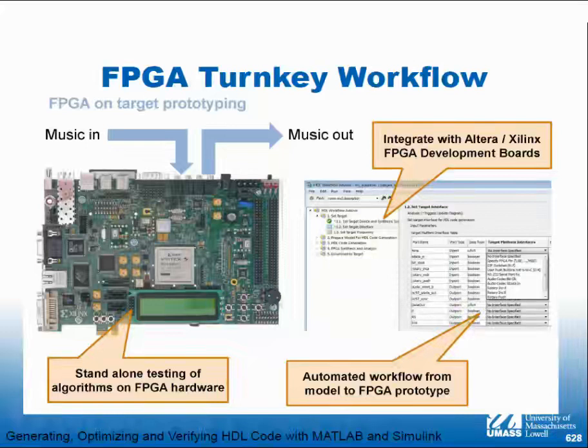We take that, we convert it to vectors, remember golden vectors, and we play them out in simulation. And it doesn't work, right? We tweak things, change filters, move things around, repipeline, and now it works. So then what we do is we take that design, put it on an FPGA, put an antenna on it, not that simple, but put an antenna on it, go out in the same field.